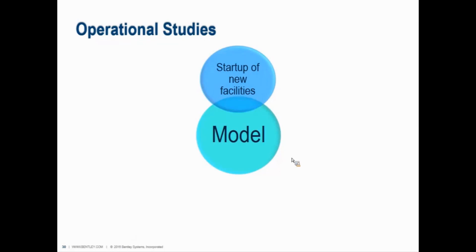And I was using WaterCAD and WaterGEMS to help answer how we turn pumps on, when we turn pumps on, when we take a tank offline to service it, to have it repaired, can the system function for several weeks while that tank is being repaired or a pump is being serviced. So you can start answering these phasing kind of things.